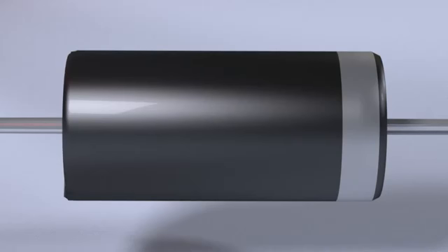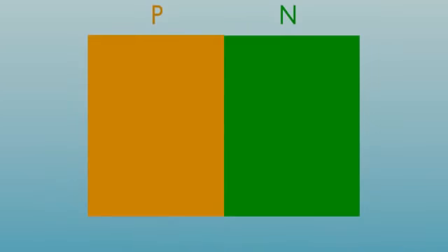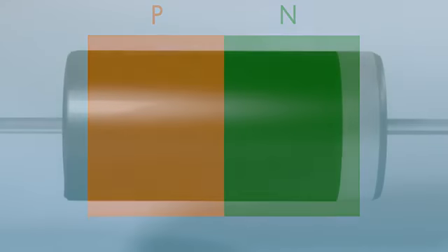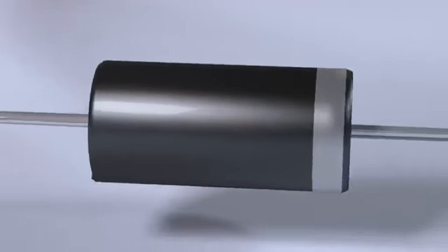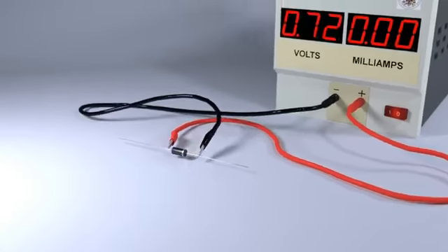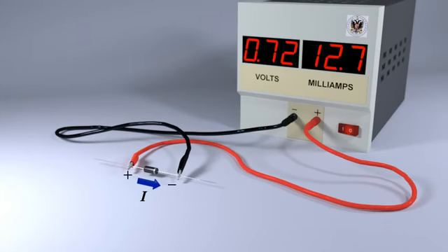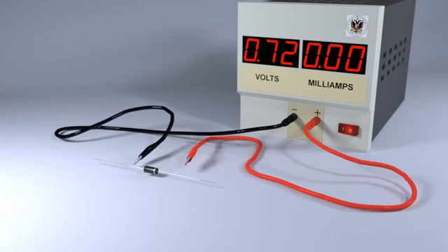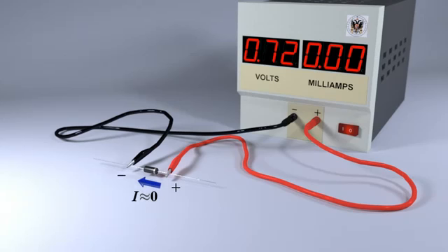A p-n junction is a structure formed by neighboring regions with different dopings, p-type and n-type semiconductors. The p-n junction is a crucial part of many devices, such as, for example, the diode. If a positive voltage drop is applied between the p-terminal and the n-terminal of a diode, a large current can be observed experimentally. If we change the connectors and a positive voltage drop is applied between the n-terminal and the p-terminal, an extremely small current, negligible for most practical applications, is observed experimentally.